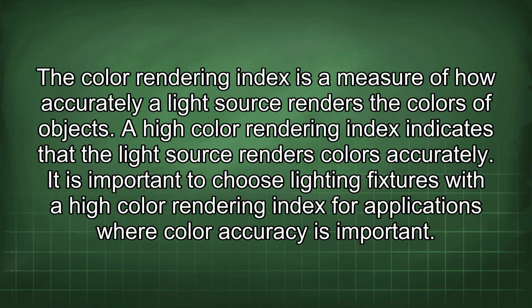18thly, considering the color rendering index. The color rendering index is a measure of how accurately a light source renders the colors of objects. A high color rendering index indicates that the light source renders colors accurately. It is important to choose lighting fixtures with a high color rendering index for applications where color accuracy is important.